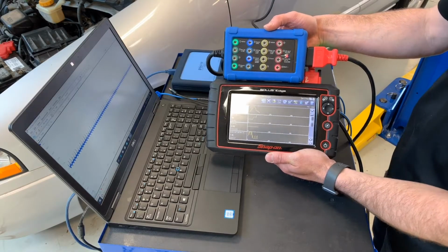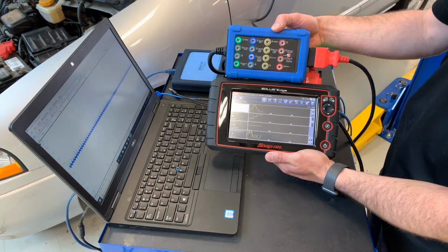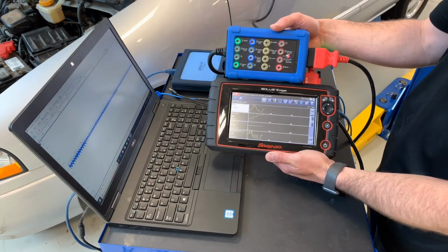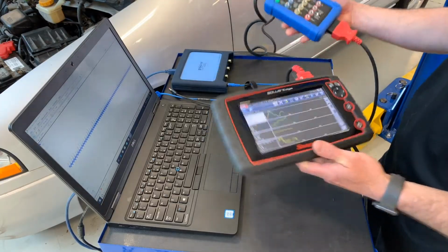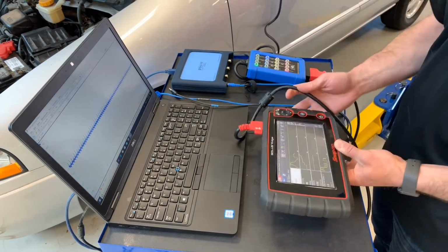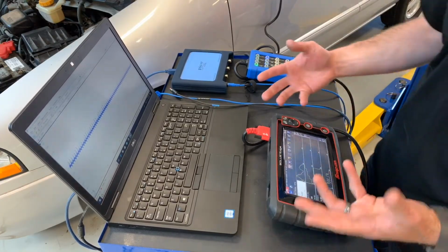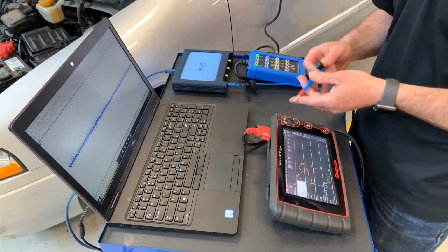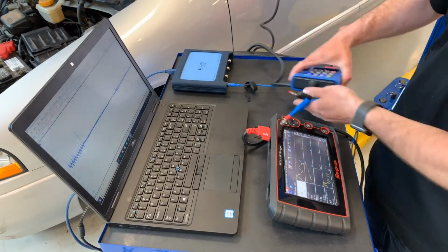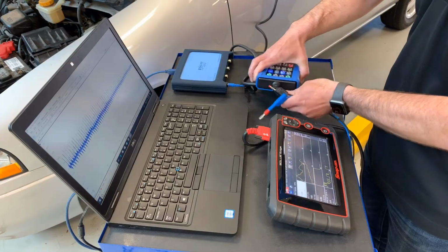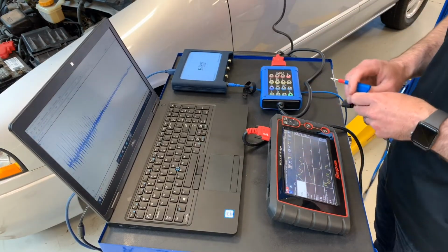So what does that tell me? Where would I use this in diagnosis? It helps me understand that there's a good connection on the data network. Data network faults have become increasingly more common. As we add more modules, we add more lines for data. And with that increase in wiring comes an increased chance that one of those wires gets disrupted. We'll go a little bit deeper with some of those faults as we talk about CAN.